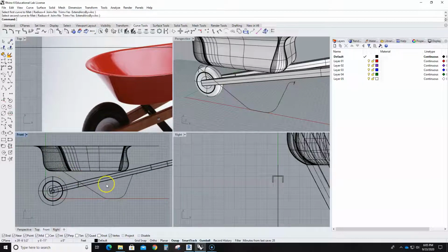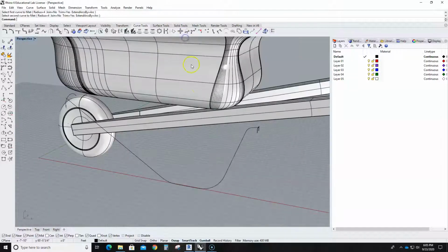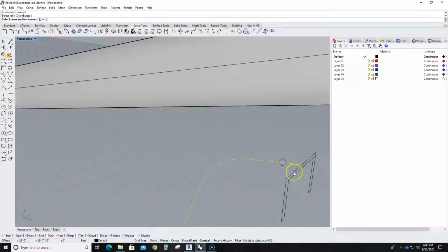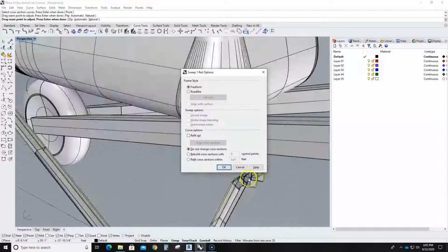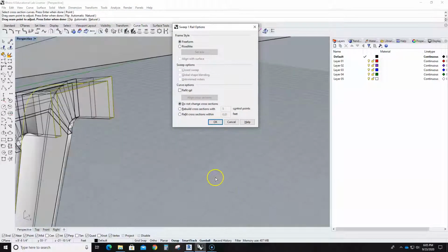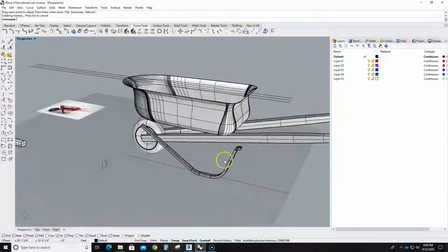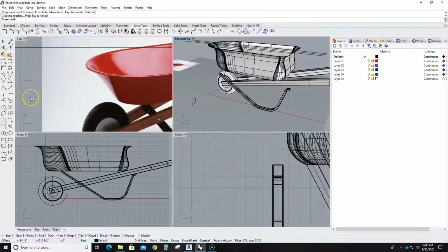All right. Okay, so let's try what this looks like as a sweep. So this part is kind of failing a little bit because it doesn't know how to quite make that turn. So I think that fillet has to be tighter. Let me see. Let me go to wireframe. Oh, there it is. Yeah, I could take that.